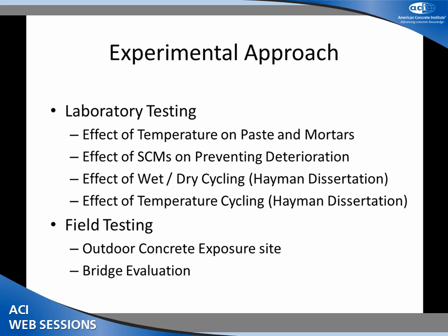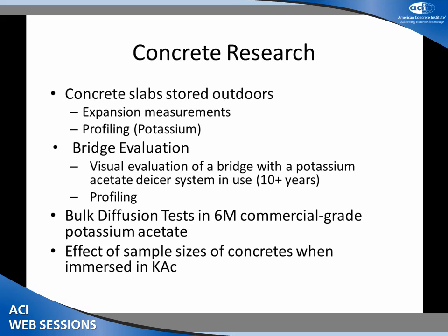So I went over all the laboratory testing, and now I'll go into the field testing that we have conducted. And that's an outdoor exposure site with concrete samples, both in Texas and also in New Brunswick. And then also a bridge evaluation of a bridge that has an anti-icing system built in. So the concrete that we did, we made 3 by 3 foot by 6 inch slabs, and we did expansion measurements and profiling to see the depth of the potassium and how far it got into the actual concrete.